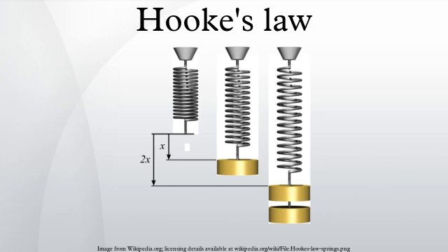Hooke's law for continuous media. The stresses and strains of the material inside a continuous elastic material are connected by a linear relationship that is mathematically similar to Hooke's spring law, and is often referred to by that name. However, the strain state in a solid medium around some point cannot be described by a single vector. The same parcel of material, no matter how small, can be compressed, stretched, and sheared at the same time, along different directions. Likewise, the stresses in that parcel can be at once pushing, pulling, and shearing.